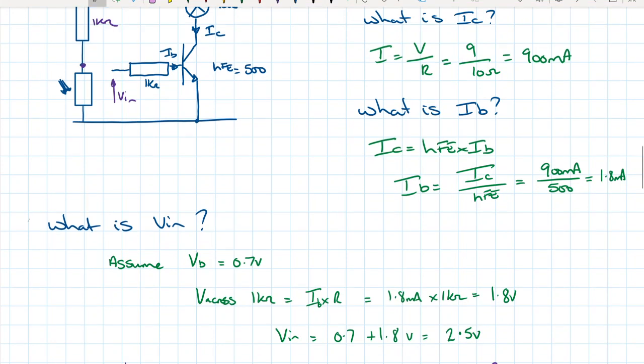So now let's look at this part of the circuit. If we look at our light sensor, given that value there of 1k, and in dark we can say our LDR has a resistance of 3k. So what I want to know is what's the voltage when it's dark in the middle of our potential divider, so that when we connect it to here, we know whether we've designed our light sensor correctly or not.